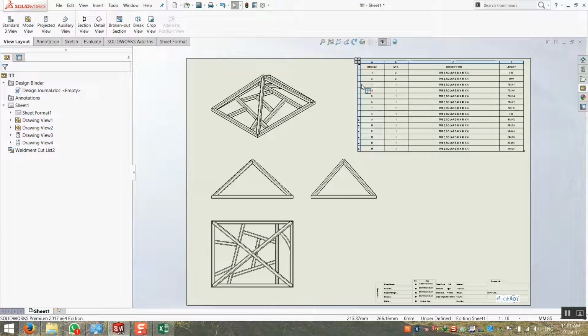What's this? This is very important because here these lines are called hidden lines. In engineering technical drawing, any hidden lines should be expressed with a dotted line. Okay? If this line were continuous, it would be an error, because it's really hidden. These dotted lines are also called dotted line in AutoCAD, and also in your graphics.